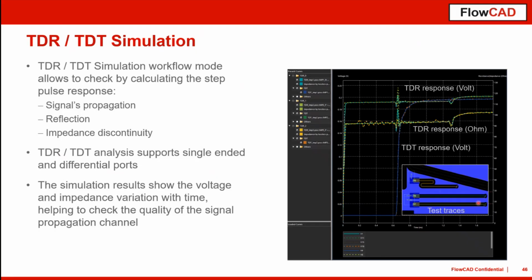On the bottom side we have the same transmission line going back. On one hand, we can see we meet the desired impedance. We wanted to achieve 100 ohms, but here it is in the range of 95, so maybe it's within plus or minus 10% of our impedance goal.